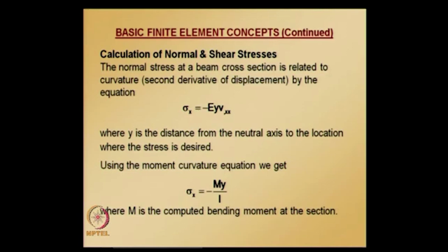And now let us look at shear stress computation. The computation of shear stress is more complicated and depends on the shape of the cross section. Shear stress can be calculated by considering a free body diagram of an infinitesimal segment of the beam along its length direction and equating unbalanced normal forces to shear force.